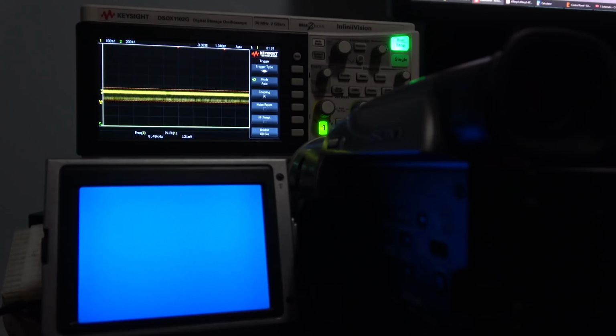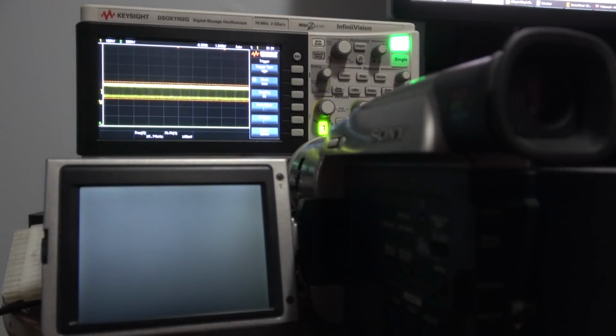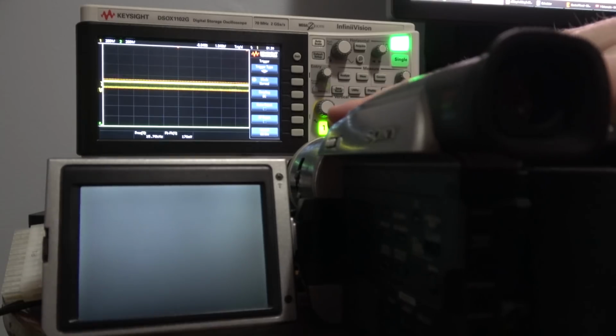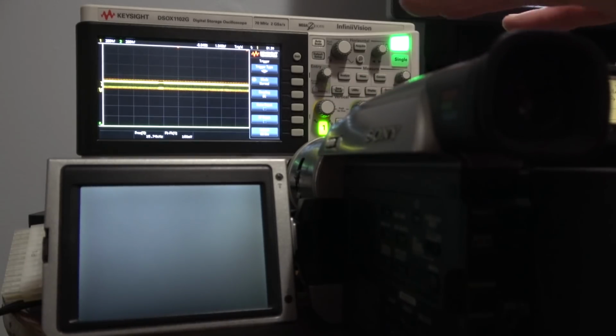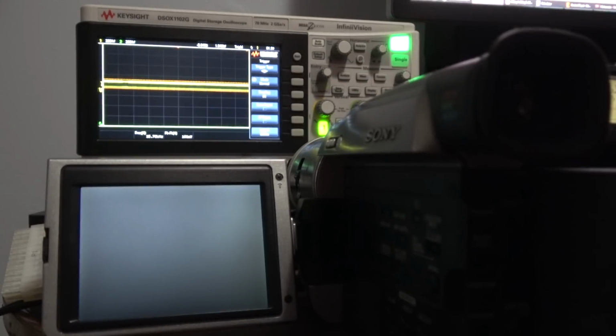I'm just going to crank up the voltage division to make up for the fact we're not using a video amplifier. And yes, this is super jank. And there we go, a black screen. Yeah, it's not the right way to do it, but it does work. And this will at least get us started. Then when we actually build the tiny little console, I'll put in a proper video amplifier, which just requires a transistor. Basically, we just need to separate the video signal that's coming off of our chip from what's going into the display. But this will work for now. We won't be able to get white. We'll get like gray, but it should work.